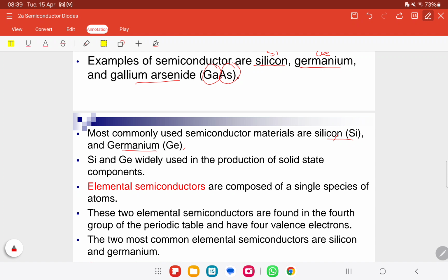Okay, and other than that, in terms of the characteristic, the silicon is more stable to fabricate. Okay, it has a better properties for the silicon, and also has higher melting point. Okay, as compared to the germanium. Okay, and also it has wider band gap and higher electron mobility. Sekejap lagi kita tengok on the electron mobility, and you can relate. Okay, you can relate with the conductivity. Also, this is a very compatible and easy to fabricate lah for the silicon.